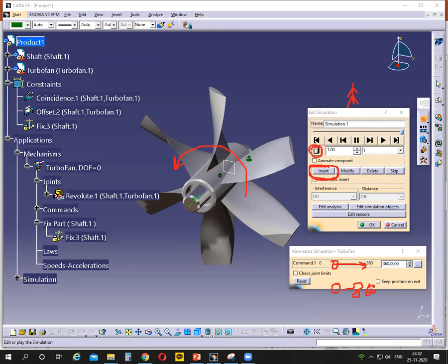After that you click this arrow. You can choose one direction, forward and reverse direction, or completely forward many times. And also this one is the time step. Time step one is very fast, so I choose 0.01 to simulate slowly.